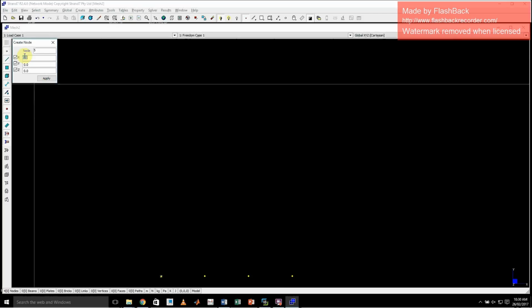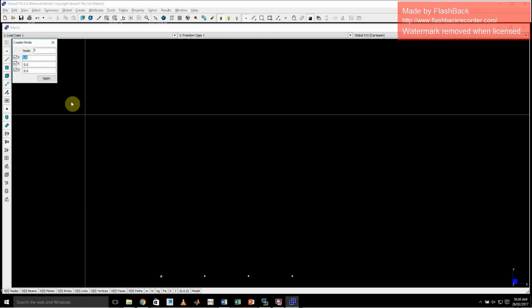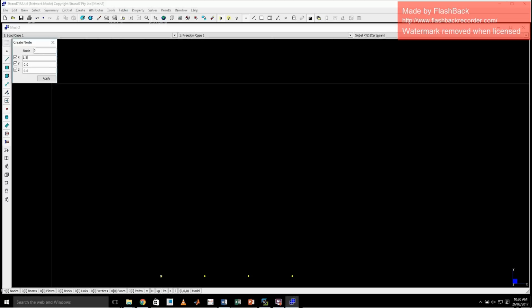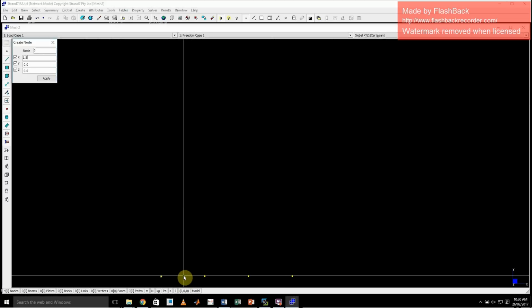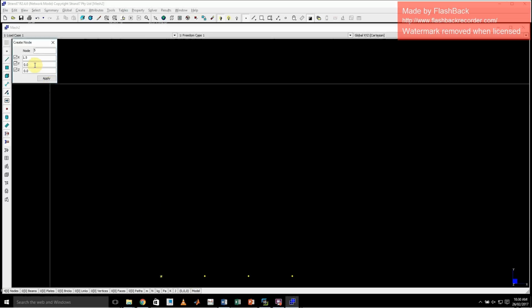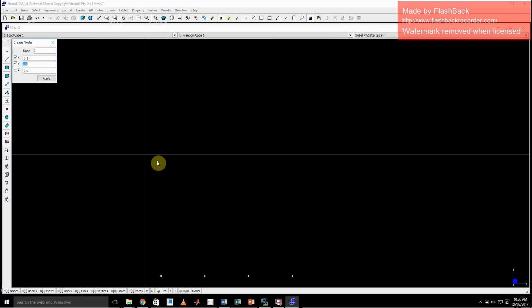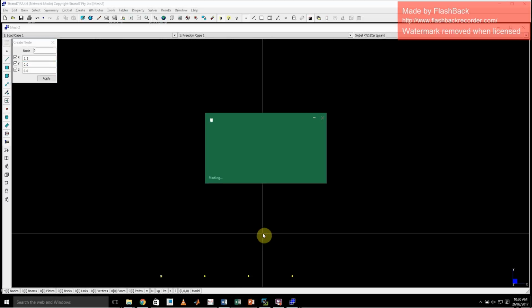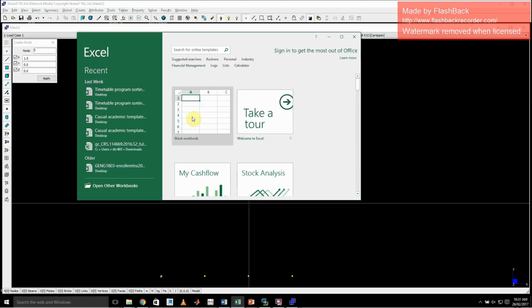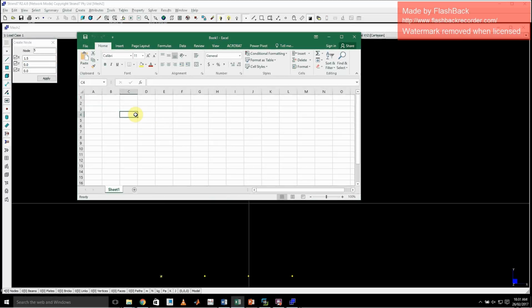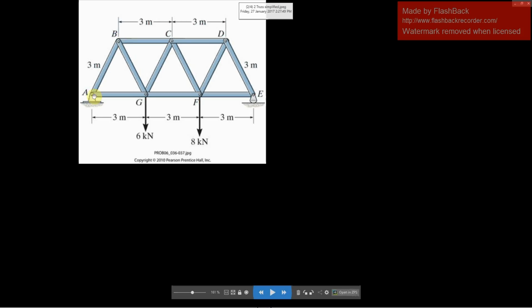One of the issues is I know when I try to make this node here that in the X it's going to be 1.5 meters because it's going to be in the middle. In the Y direction I don't exactly know where it is yet, and I'm going to have to work that out. Simple Pythagoras is going to do this for me. You're going to equal, that's 3 meters, that's 1.5, and I want the length of that.